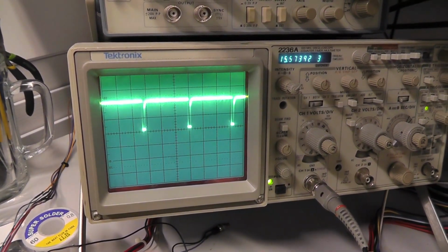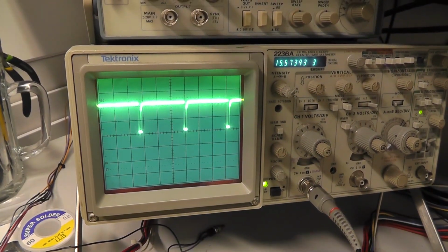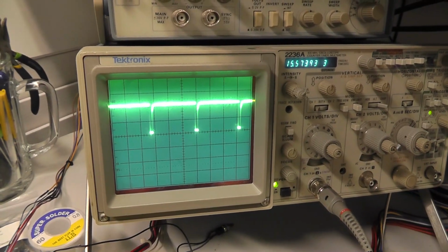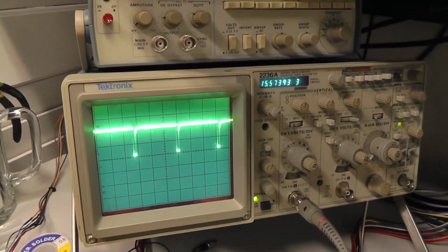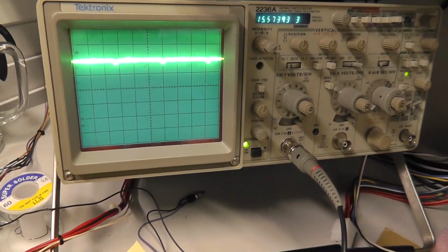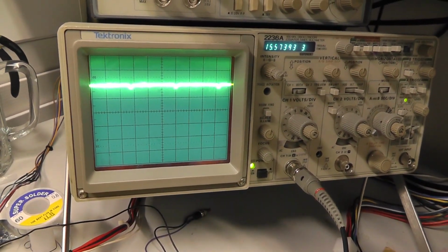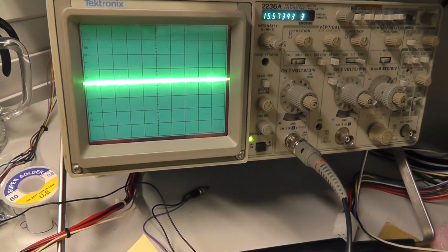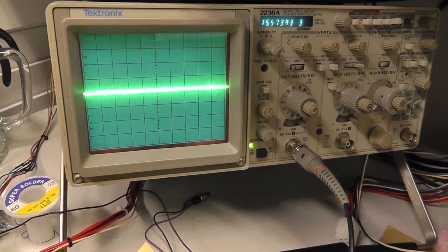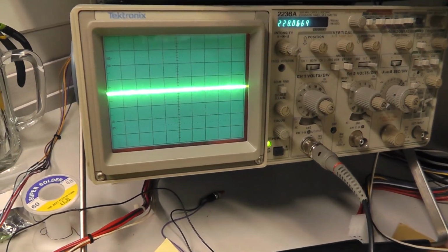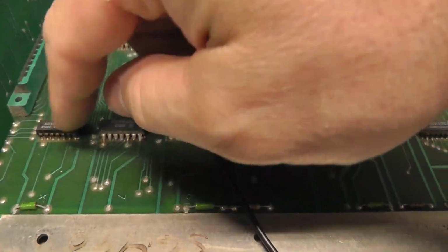15.5 kilohertz, and it's going all the way from 0 to 5 volts basically, the signal. And then if I come to pin 3, 1, 2, 3, that's what our output on 3 looks like. And pin 2 is low. I don't know what a 7432 is. So I think that's our problem. I don't think that it should look like that, the 7432.